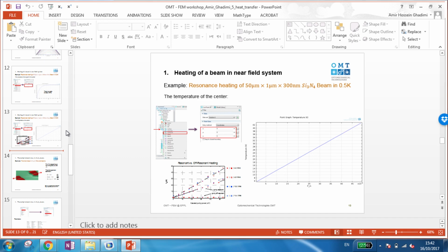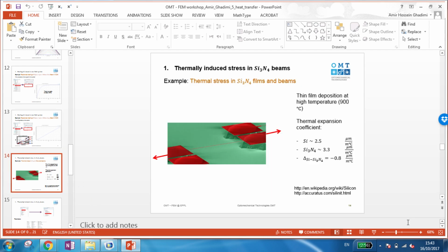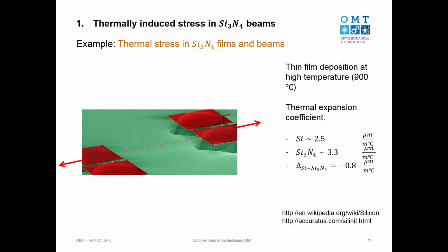For example, why? Because it's an amorphous material. For gallium arsenide, we know most of the stress comes from the lattice mismatch between silicon and gallium arsenide lattices. Here, there is no lattice, and we have some ideas, but the problem is there's not one source for this high stress. There are different factors coming into play, and this is one of them. It's called thermal stress.